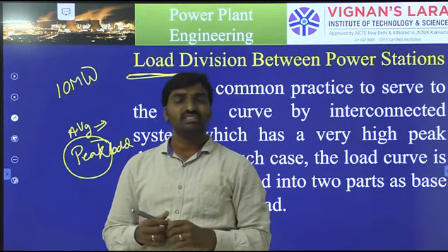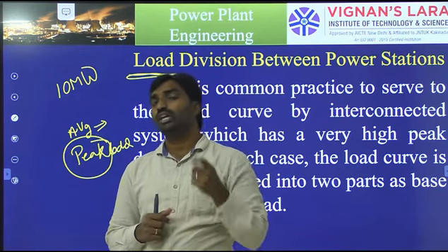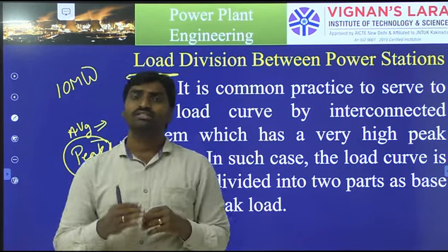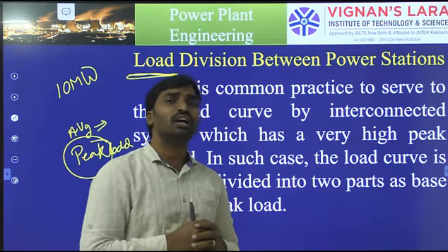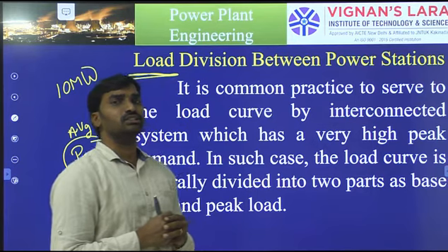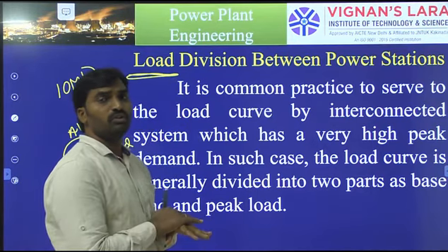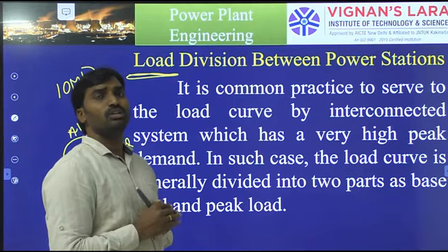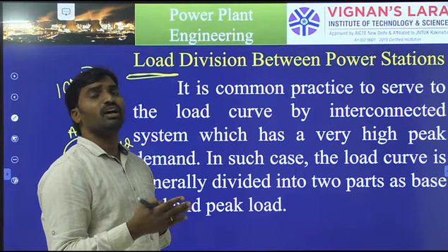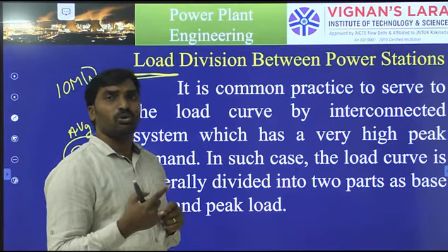So that's why the entire day we require the minimum power, and that is known as the base load. And at some particular times we need the maximum load, so that is known as the peak load condition. A simple thing: if you want to run the power continuously at the same level, that is known as the base load. If you require a special or high power at particular times, that is known as the peak load.